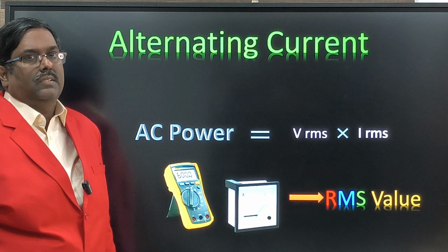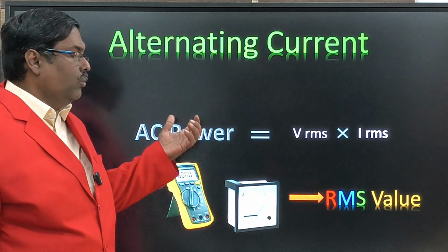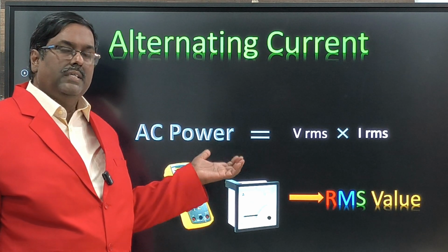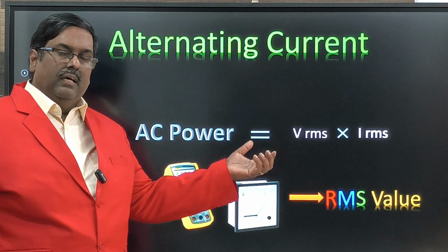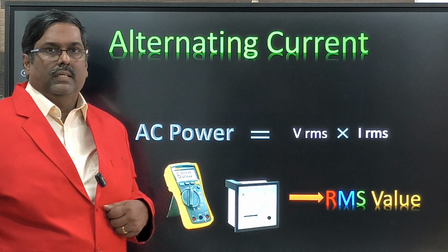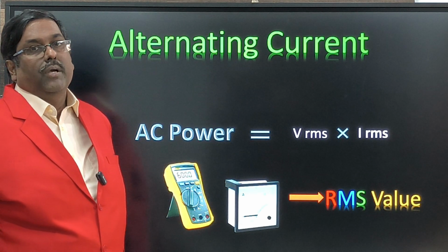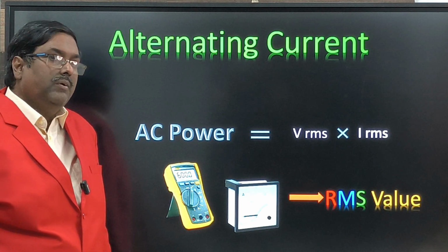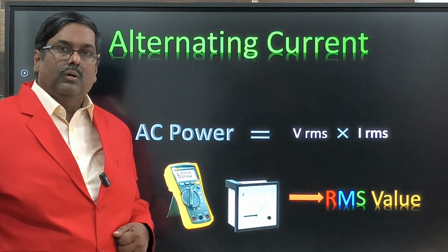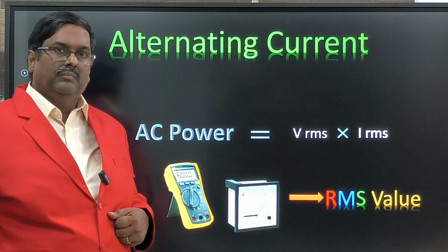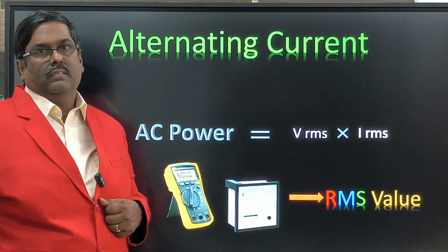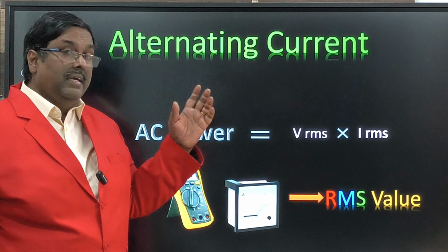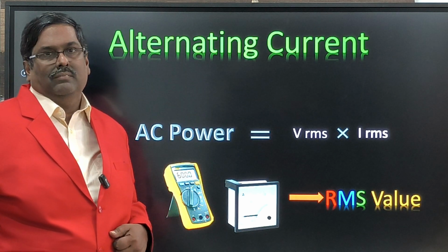Why is the voltage increased? For example, 230 volt AC is there. You convert AC into DC by rectifier diodes and a capacitor. Then the output will become 320 volt DC. You imagine, you give only 220 volt, but you are getting 310 volt. How is it increased in DC? DC will take the peak voltage.